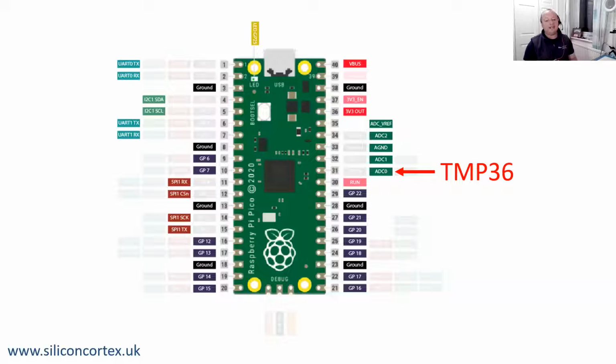If you bought an ADC that says 12-bit, I wouldn't count on the bottom 4 bits being even close to stable. Well, my experience was certainly to say the bottom bit and maybe the bottom 2 bits. I wouldn't normally throw away the bottom 4, but yes, I take the point.